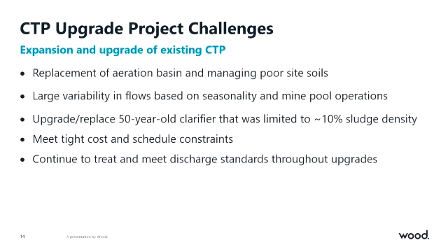We had to manage large variability in flows and water quality, lime demands associated with seasonal variability and the way that the mine actually was operated, whether it be pumping water back or for just receiving gravity from the mine, which again, lower pH, much higher concentrations of metals. We had to find a way to work around and integrate the clarifier into the process because we didn't want to replace it.